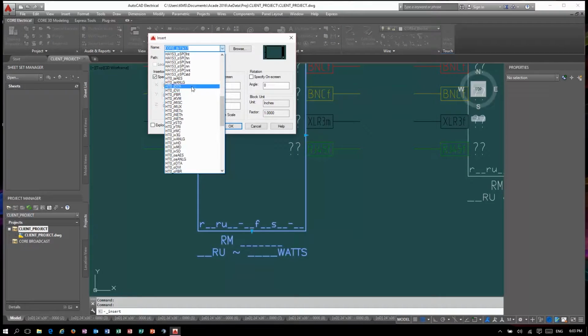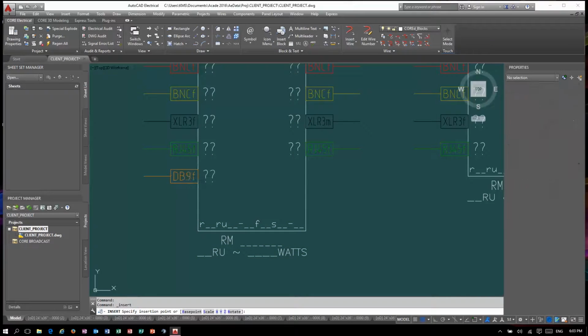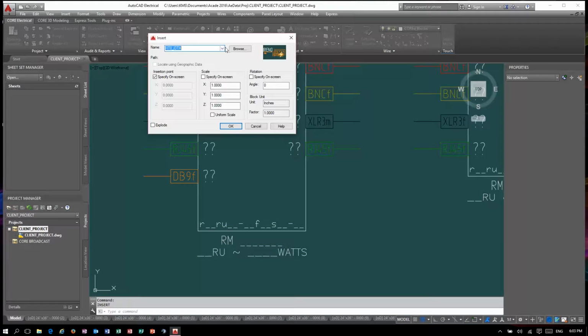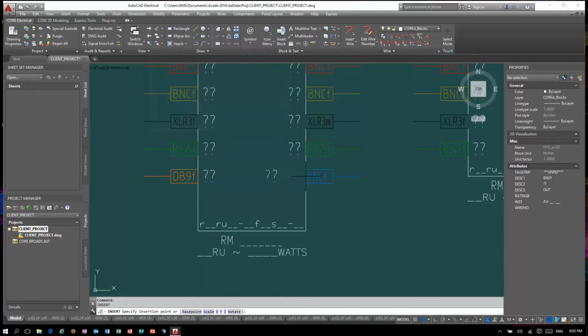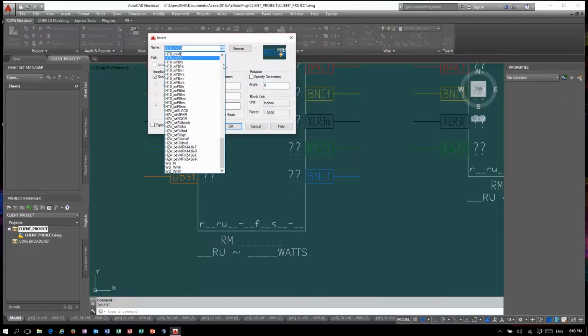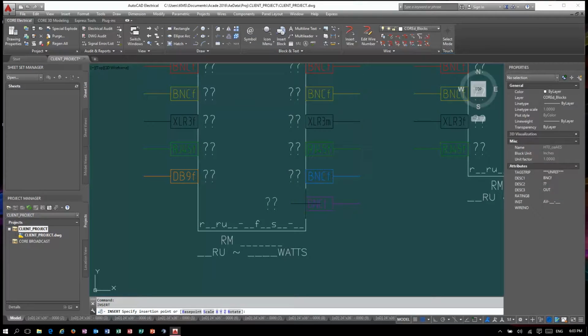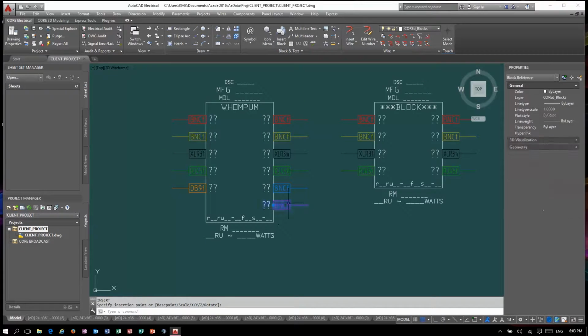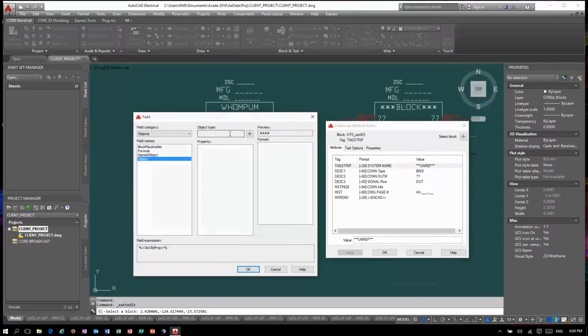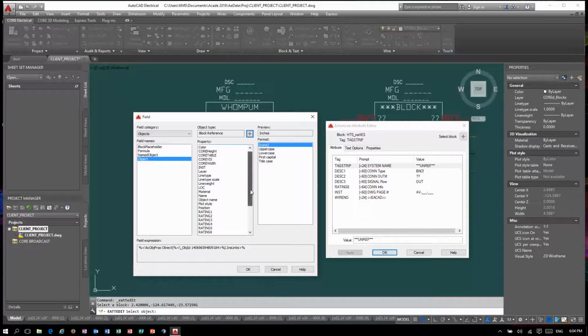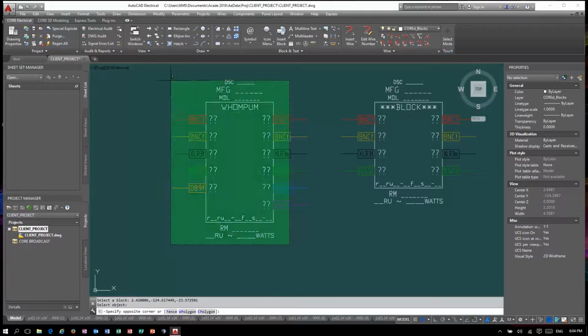It verifies common tasks like wire number and device name duplication, one-to-many, many-to-one, and intersection of wires, mismatches between label pointers and wire number references, internal design compliance and methodology, file and data structure verification, and authentication. Our electrical wire run list tool then collects and processes this raw data and performs a multi-level hierarchical search for audio, video, data, and networking components.